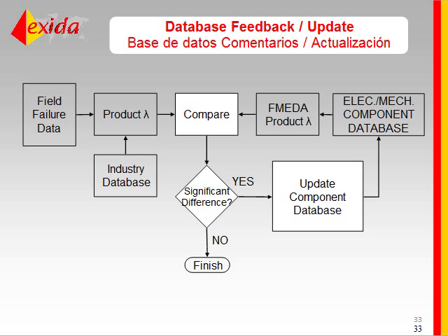No component database would be worthwhile if it wasn't constantly being compared to real results. And I will tell you that the research group I work with typically at Exida constantly compares real field failure data and the product level failure rates to the FMEDA results. I consider this an advantage of the FMEDA technique because it generates product level failure rates by adding up all the failure rates of the modes